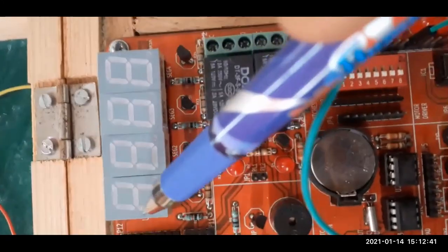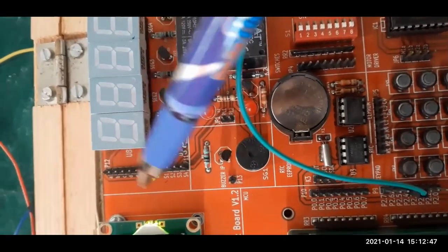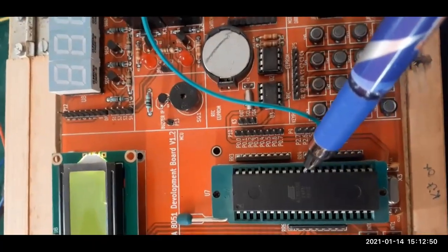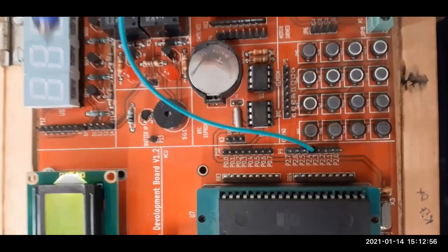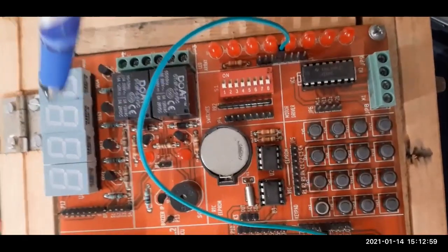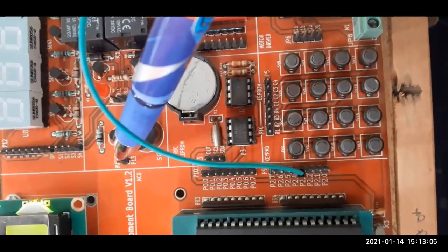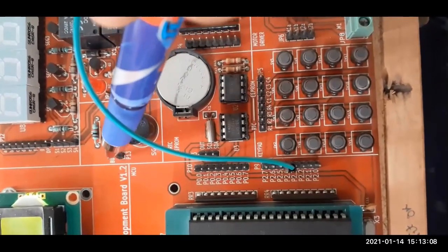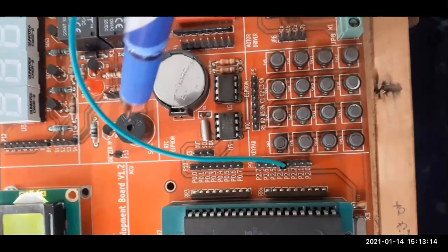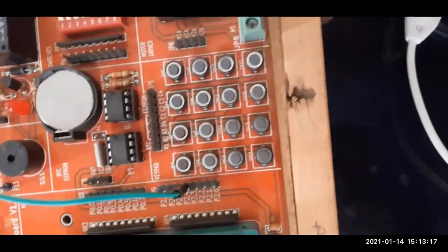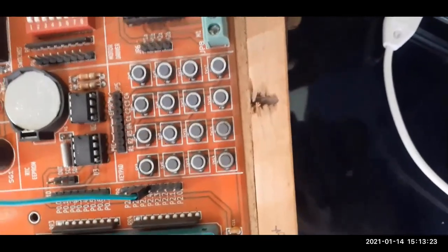Okay, similarly here we can also interface 7 segment display, for which pins are taken out here. We can interface these pins with port pins of 8051, depending on your requirement. You can also operate this 7 segment LED display. Okay, so this is buzzer. So we can connect port pin here, and if it is 1, it will sound this buzzer. If this is 0, it will turn off the buzzer. Okay, so this is onboard battery. So these are major IOs.